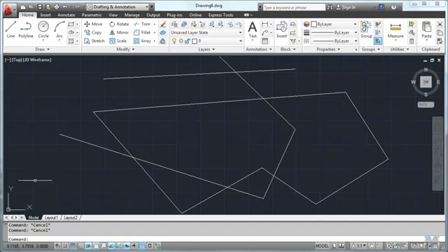So you've probably noticed that the software is working in this XY coordinate scheme, right? If you look in the lower left part, the drawing coordinates, see when I move the mouse around, I've got the line tool on. It's giving me the same numbers right next to the cursor as it does in the lower left.